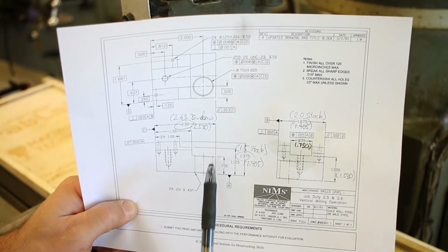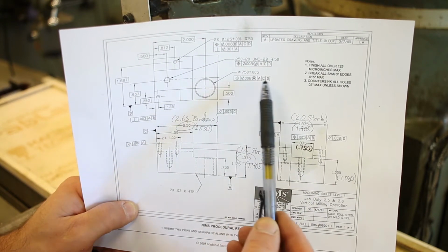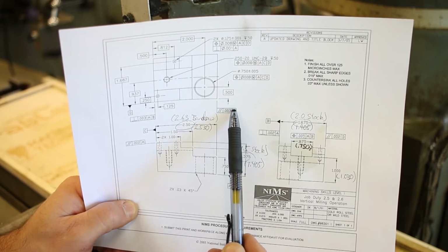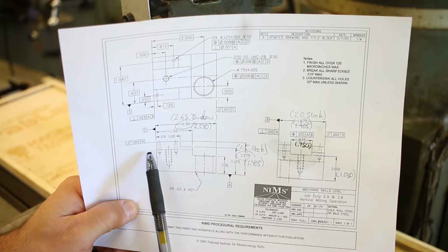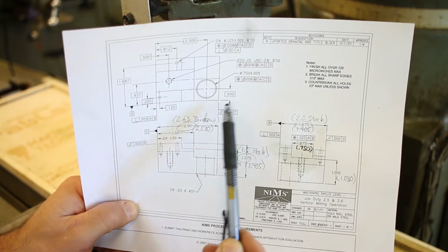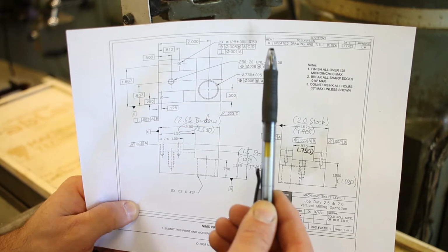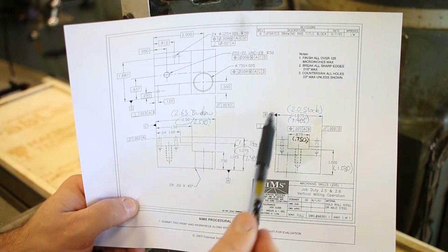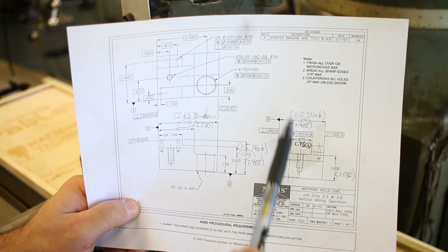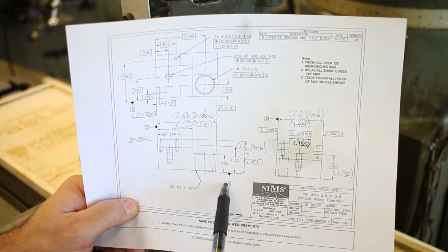operations. In the case of the NIMS Step Block, if we look at all of these GD and T callouts in the feature control frames, we can see that there are a number of places where we have datum references. In some places there's only one or maybe two datum references, and in other places there are even 3 datum references, a true datum reference framework. So if we take all of these GD and T callouts and retrace the logic, we'll find that all of these GD and T controls ultimately reference datum A down here.